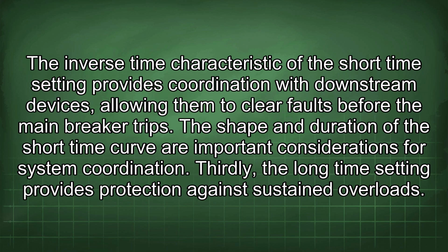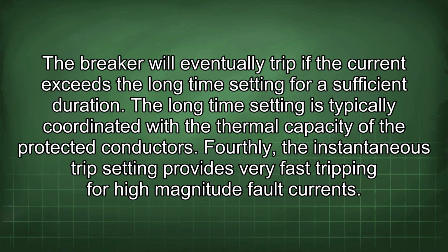Thirdly, the long time setting provides protection against sustained overloads. The breaker will eventually trip if the current exceeds the long time setting for a sufficient duration. The long time setting is typically coordinated with the thermal capacity of the protected conductors.